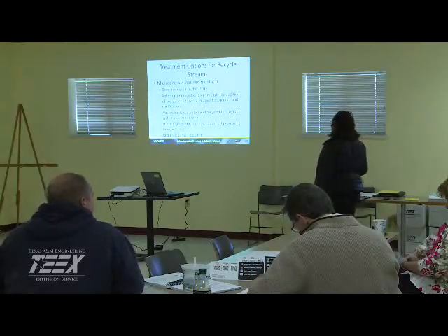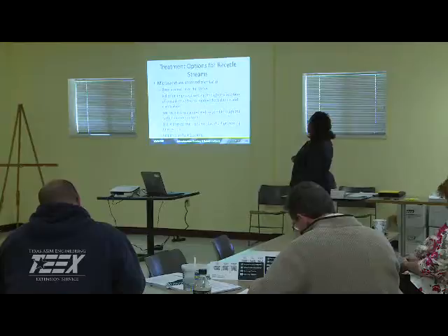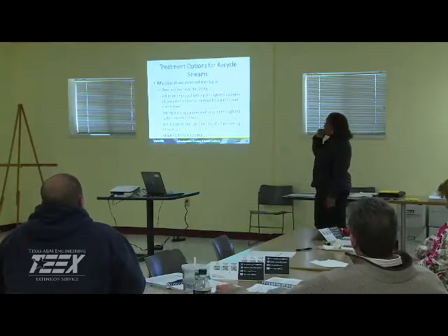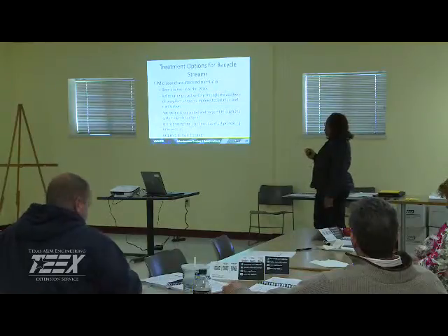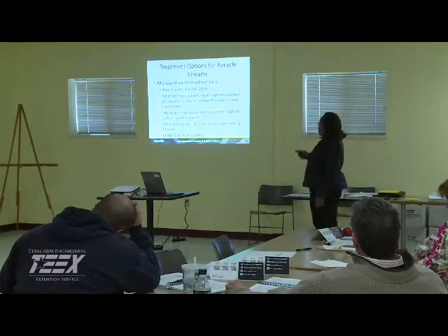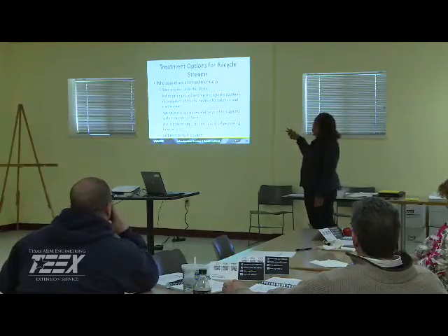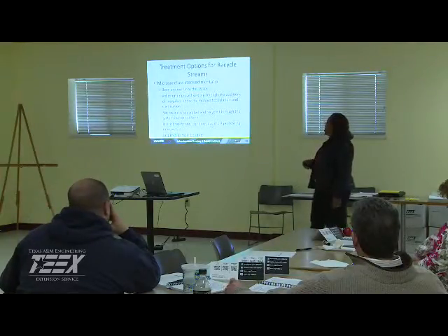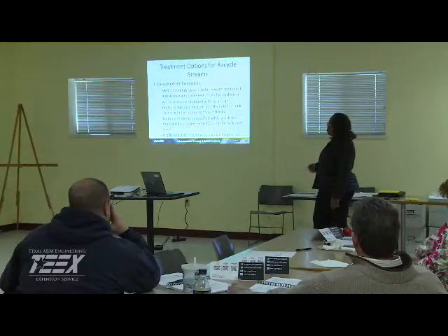Treatment options for recycled streams. Micro sand assisted filter sedimentation has been around since the 70s. Again, this relies on improved settling through the addition of coagulant, flocculation, as well as clarification. Your micro sand is separated and recycled through the system numerous times. One advantage: quick process startup. However, a disadvantage: short processing time. It also requires a small footprint.